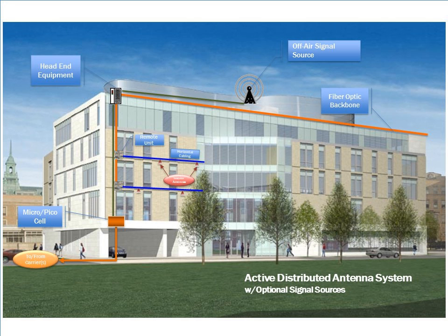And then basically all of that gets combined into a master unit. And then from the head end here, it goes out on fiber. From there it's connected to a remote unit, which is typically sitting in a closet. And then from that remote unit, we go out to antenna points either with Cat 6A or with half-inch coax. So all we're doing is basically passing the signals that they're providing us.